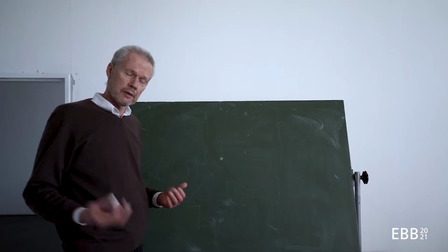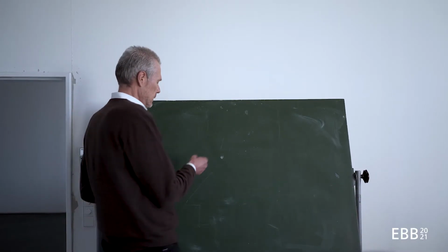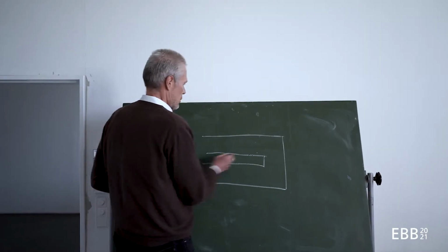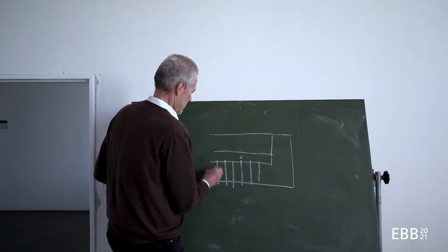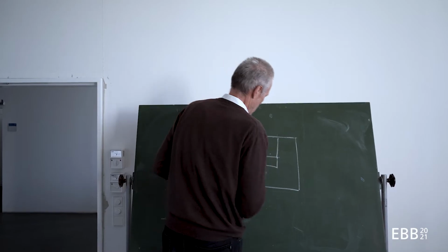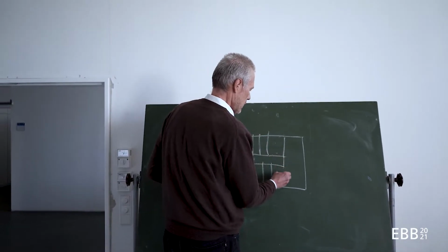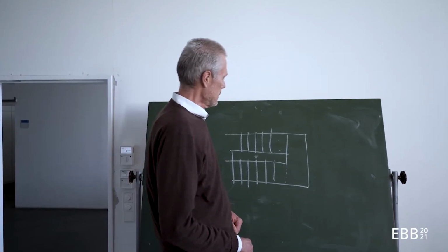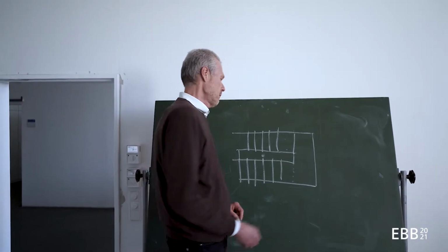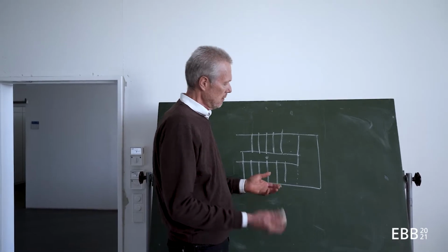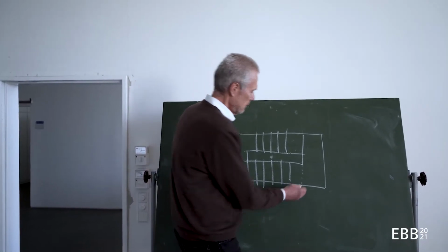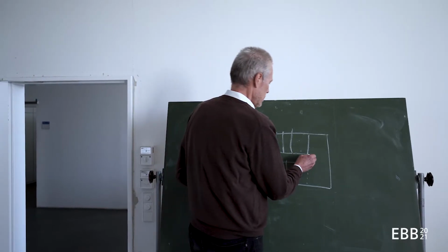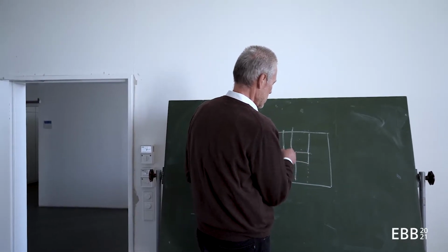So very often, if I want to have a straight or a knuckle line, I will have a stair which looks like this, rather than having a straight line of two corresponding steps here. This would represent then ideally the knuckle line. It might be a little on the side. And I also have to take into consideration here the stairwell.